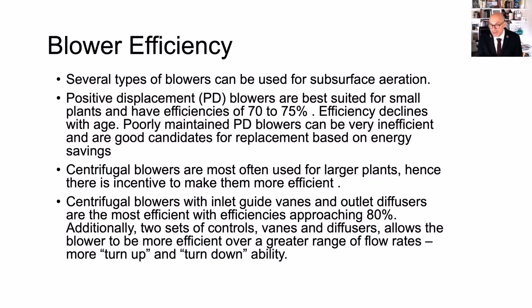Whereas if you have a centrifugal blower, you always have the risk that if you have too much back pressure on the discharge side, well, it's not a perfect check between the rotor and the casing, because otherwise it will touch it. And so at some point you're going to have the blower being unable to overcome the discharge pressure. That condition is called a surge. When the blower surges, you will not be able to move the air forward and the blower shuts down because it starts vibrating and it could effectively destroy the basement of the blower.